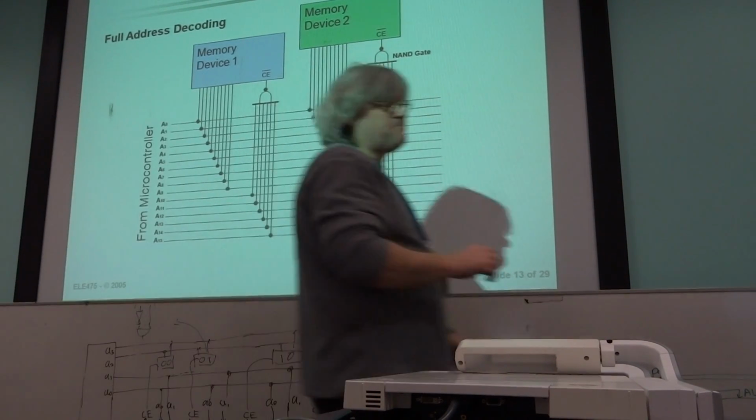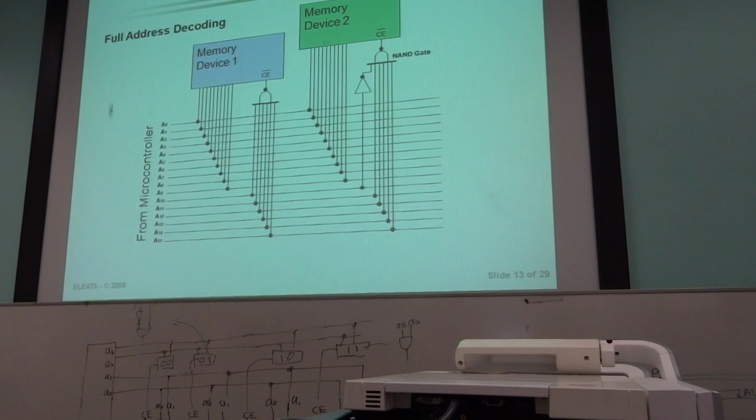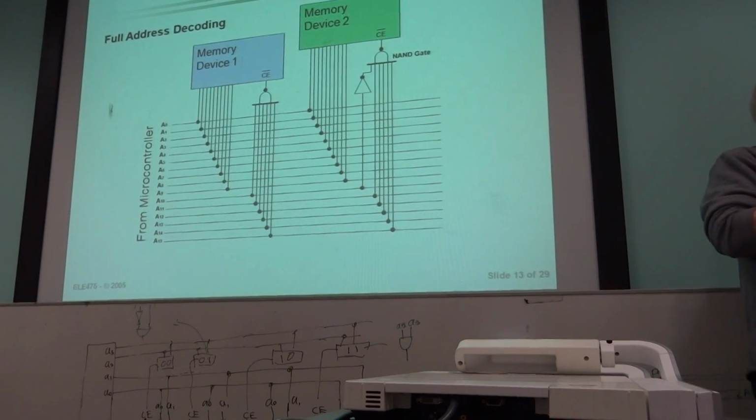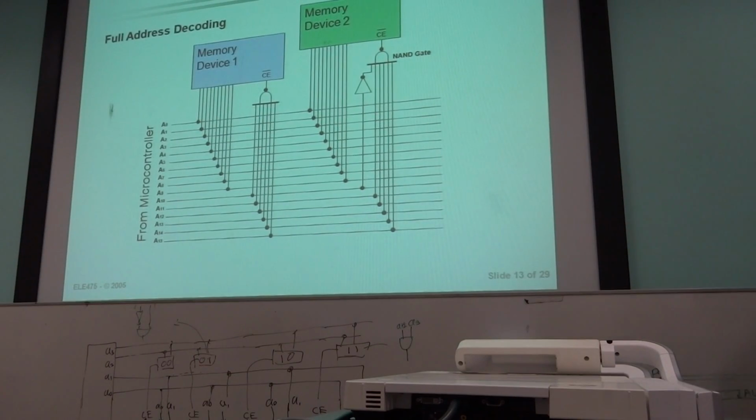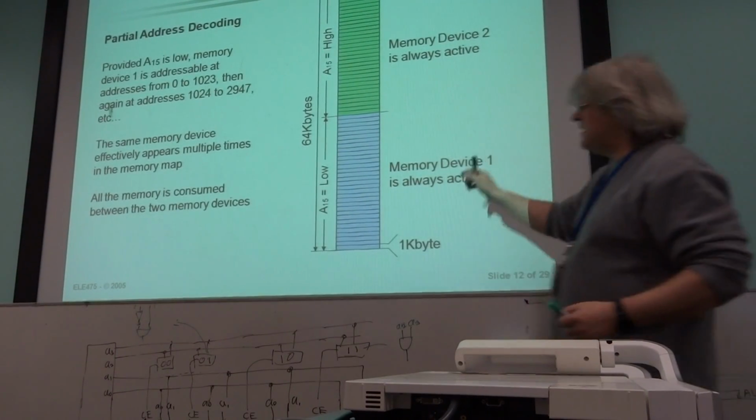But you could just write on the empty ones and leave either side of it the same. I think what he's trying to say is, can you not use combinational logic with the other ones too? Yes, you can, absolutely, yes. And I'll show, there are compromises. But as it stands, if those other address lines you want to use them for other purposes, and you're not using them as part of an address bus, they're just lines to fiddle with, you can do that. But the point is, if we go back to that full address decoding, I haven't really shown it.